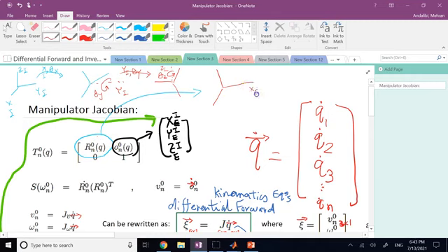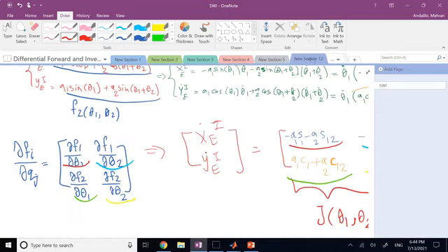For example, this is x of end-effector, this is z of end-effector, and this is y of end-effector. You have to keep track of that and see, with these three angles theta x, theta y, theta z about absolute x, y, z, when I give you a rotation matrix of E with respect to I, how do you get those three angles, theta x, y, z, back? And if you remember, for that, you have to do the inverse problem.